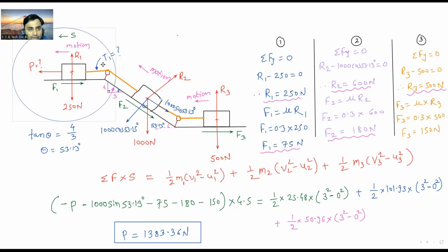Okay, to calculate the T1, this much of free body diagram you need to consider. So if you take the section like this much of free body diagram, then the string is cutting down and then you can show the tensile force in the string.